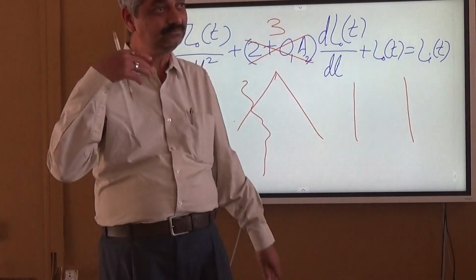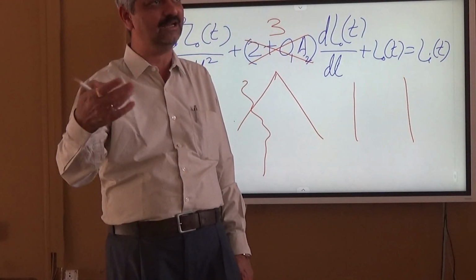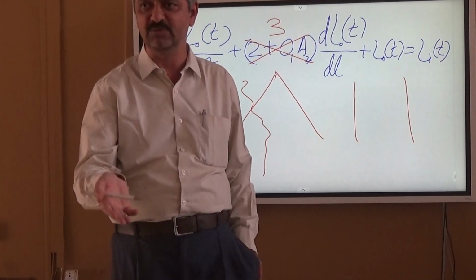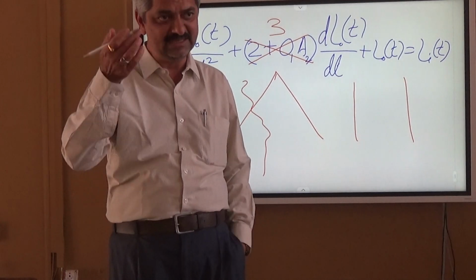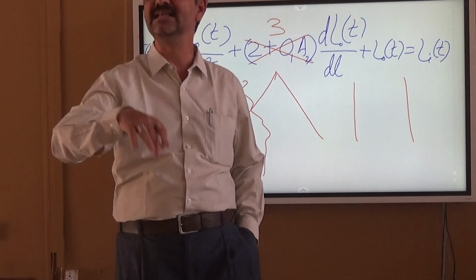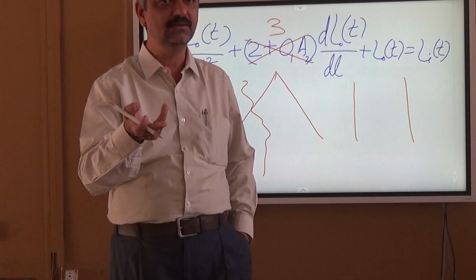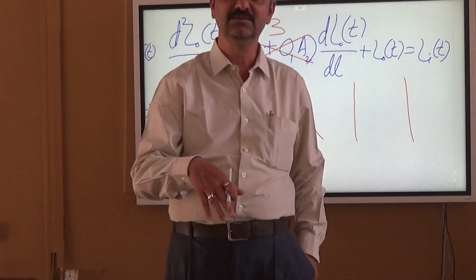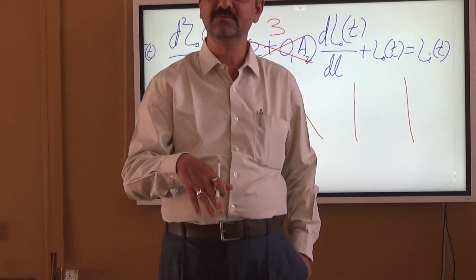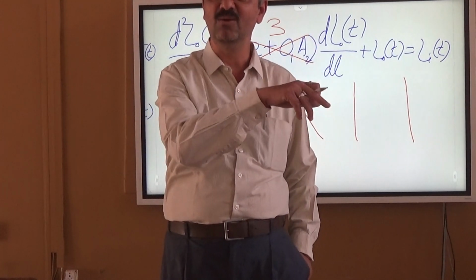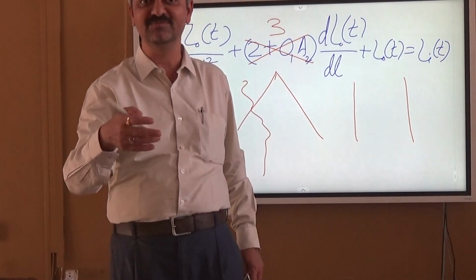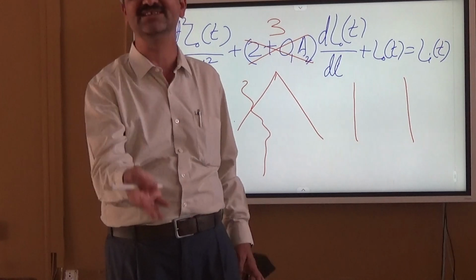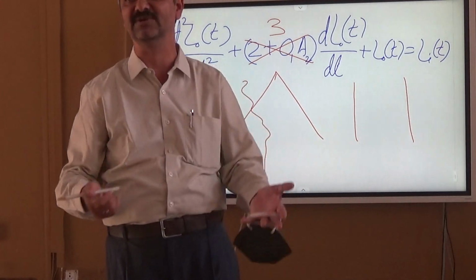See, we say that for a capacitor, Q equal to CV. We differentiate, so current dQ by dt is equal to, we say, C dV by dt. But why? It can be C dV by dt plus V dC by dt, because we presume that the capacitance is constant, but that also may change. And in that situation, the thing will be different.